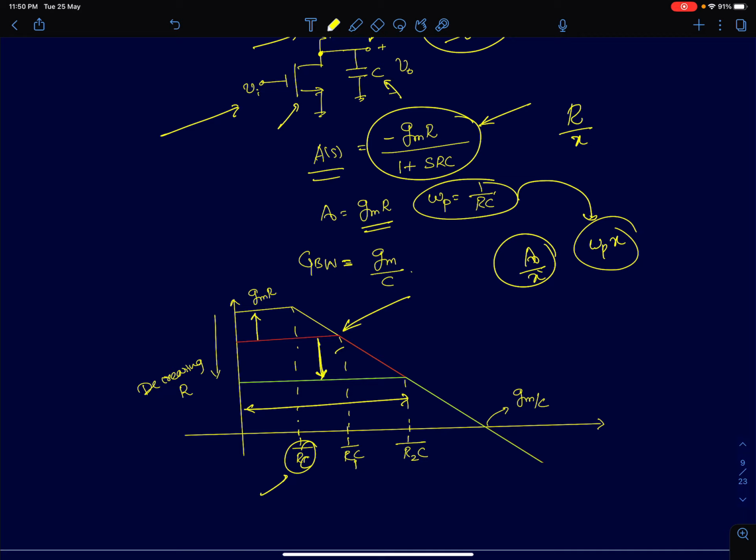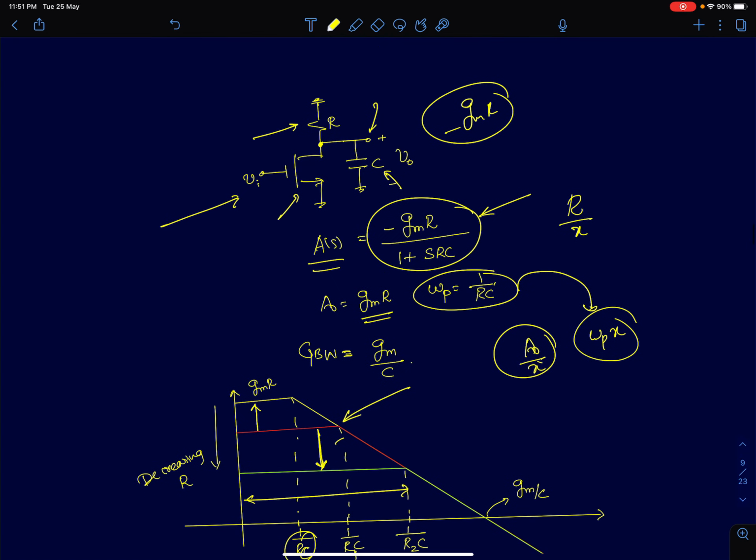What we are trying to say is that it looks like negative feedback amplifiers help in extending the bandwidth, but it is coming at an expense. It is coming at the expense of the DC gain. And what we are trying to explain here is that to get that benefit, one doesn't necessarily have to go for negative feedback amplifiers. You can get that gain bandwidth trade-off even in an open loop amplifier as well.